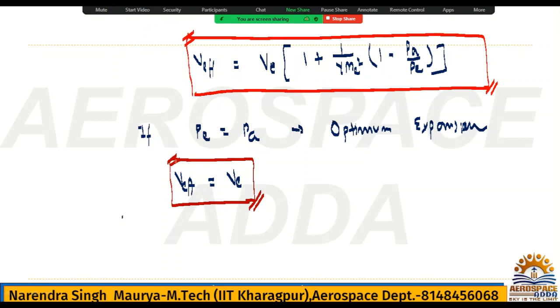The propellant enters the combustion chamber, mixes and is ignited. The gas produced is heated by chemical energy released during combustion and expands through the nozzle. The temperature of gases in the combustion chamber you will denote by Tc, and because there is no flow intake, the velocity in the combustion chamber will be negligible.